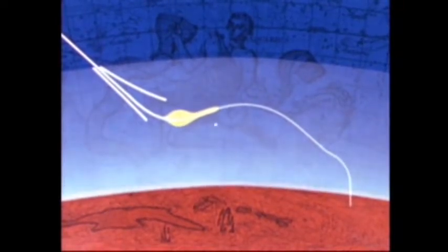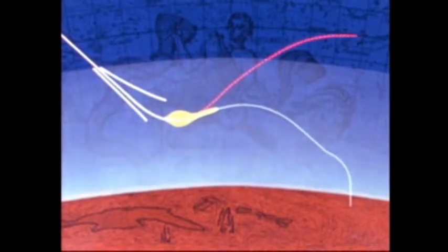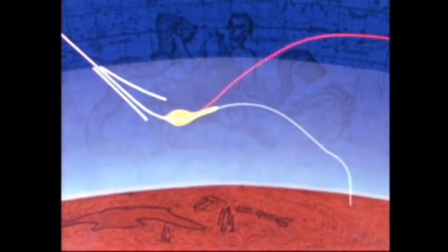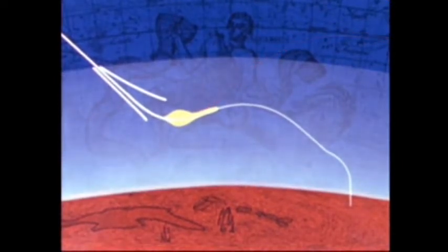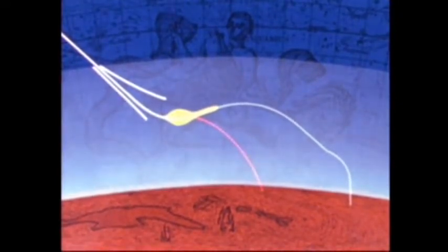During the first 70 seconds of this control period, any error or failure to correct an error could result in what is called, in great understatement, a non-recoverable situation. That is, too much lift-up could put the spacecraft and crew into an orbit that would last beyond the lifetime of the command module systems. Too much lift-down could take the spacecraft and crew beyond the stress and heating rate limits and result in destruction of the command module.